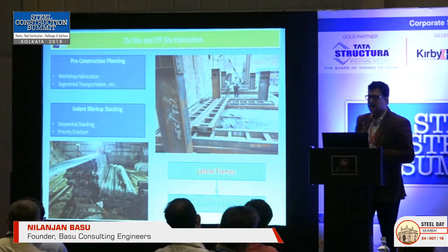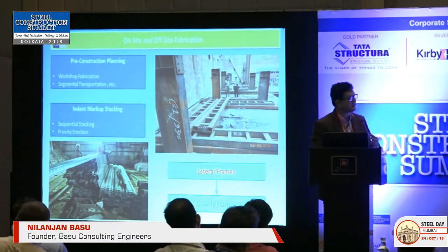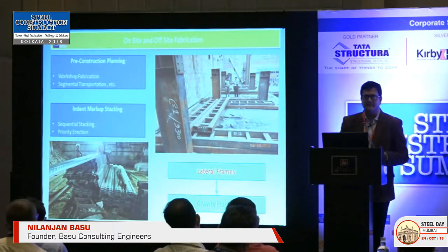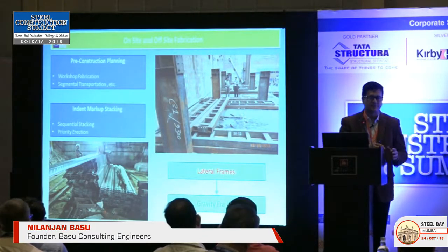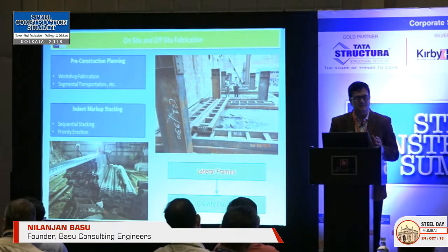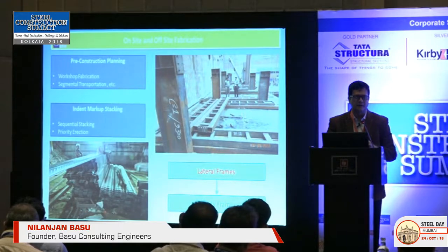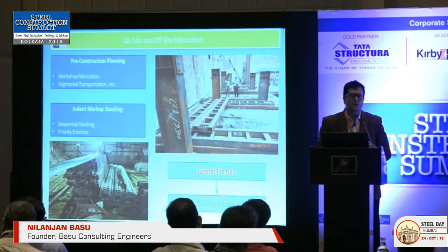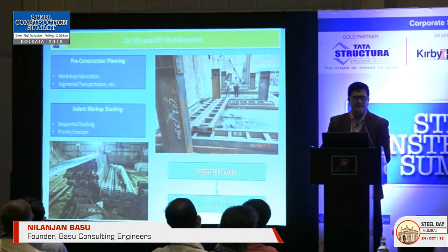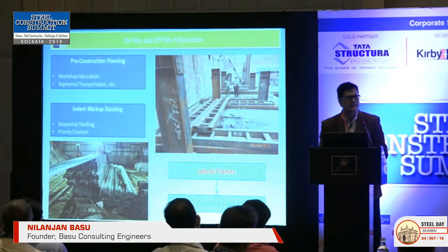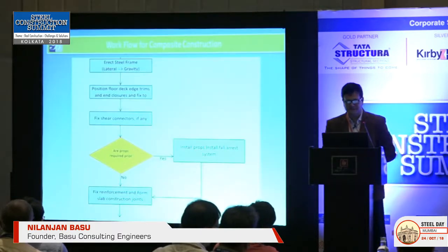Essentially, in a building, I would prefer to erect the lateral frames first, followed by the gravity frames. I just explained the difference between lateral frames. Because once the lateral frames are up, you know that your structural systems, if they can both go parallelly, but you can't have the gravity structure up before the lateral. So once your lateral and gravity is up, even during construction phase, you know that even under adverse weather conditions, your structure is going to remain safe. It will not yield to any of the forces.